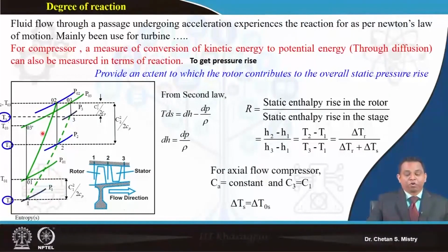For a compressor, the measure of conversion of kinetic energy into potential energy through diffusion can also be measured by using the reaction parameter. That is what we get in the sense of pressure rise. This gives you an idea of the contribution to the pressure rise by both the rotor and the stator.